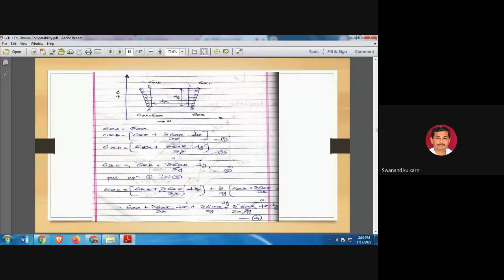Okay. So here, now a small substitution we are going to make, because in this third equation we have identified the stress present at point C, and here we have taken the reference of the stress present at point B. Now let us substitute this particular equation 1, because equation 1, which is shown here, is for sigma xb, the stress present at point B. So this equation 1 we are going to substitute here.